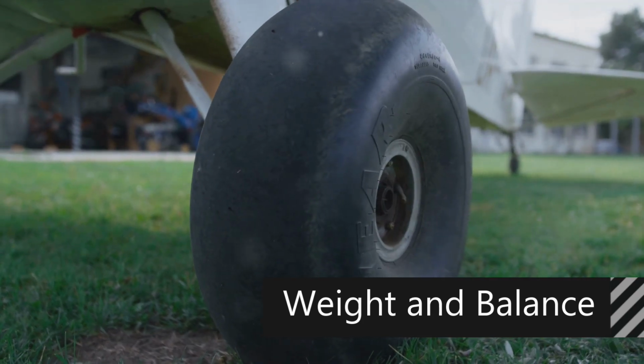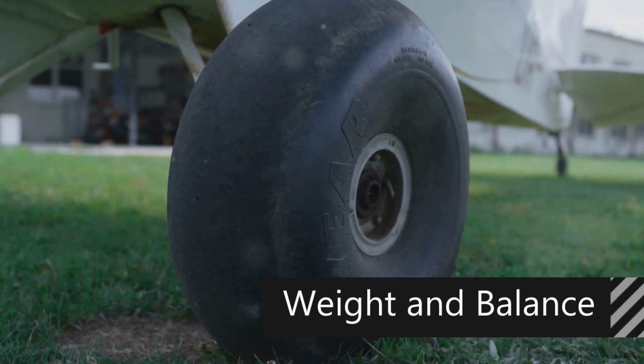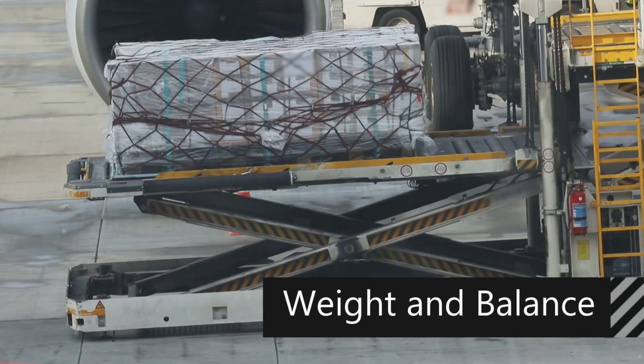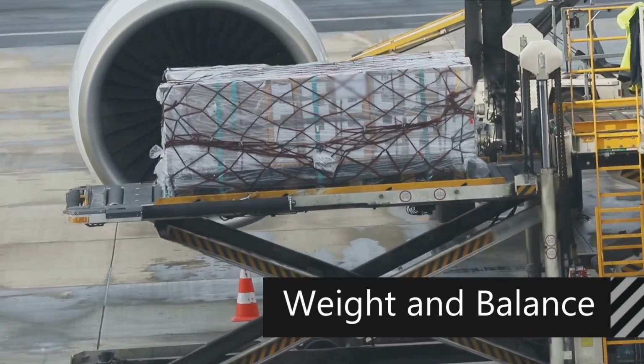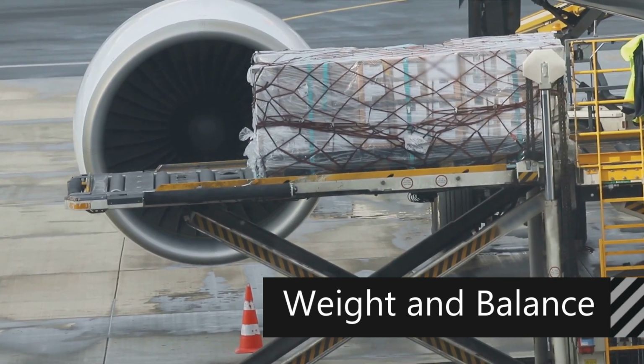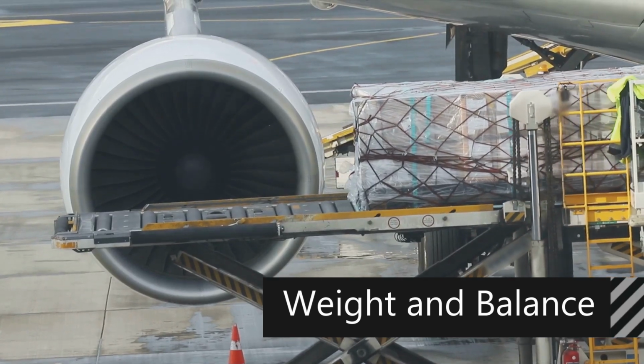It is important to note that the natural correction for a longitudinal imbalance by the pilot is a compensation change to remove excessive pressure on the control. Excessive compensation, however, has the effect of reducing not only aerodynamic efficiency, but also the range of travel of the primary control in the direction in which the compensation is applied.